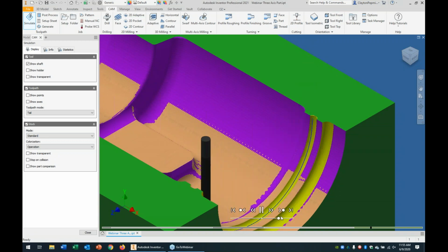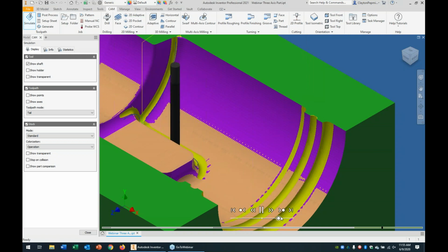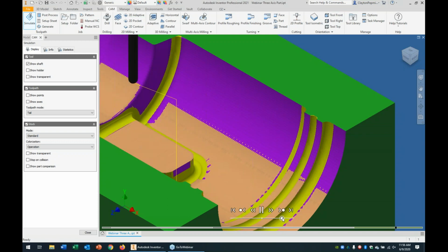So you should be able to eliminate any kind of whiplash with the tool by using their pencil cycles. Their pencil cycles start at the outside and work their way into the corners. I think you'll be able to see it on this radius. See, it's kind of on the outside. It's going to work its way towards the corner. It's also going to work it from both sides, the vertical side and the wall side. You might be able to see it more over there. Maybe not quite so much. Yeah, you can see it working from the floor side there. Then eventually it's going to come in and start working it from the wall side.